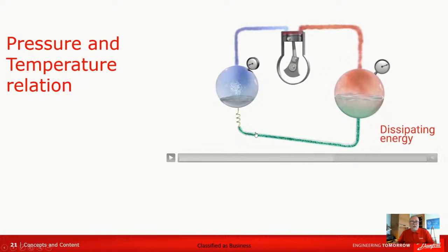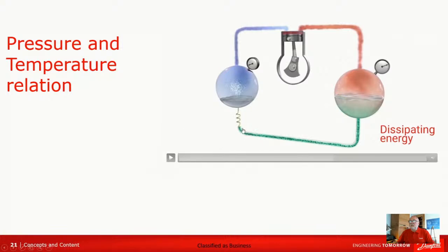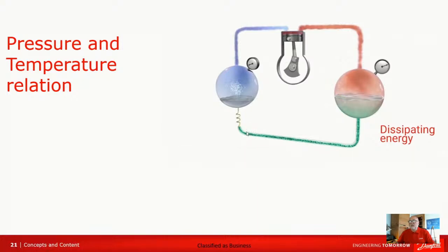And if you take an ordinary fridge, you'll actually see that there is a tiny little receiver sitting just in front of the expansion device, and it would always be in front of the expansion device, where you of course have the liquid part of it.